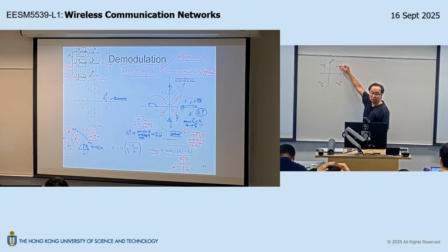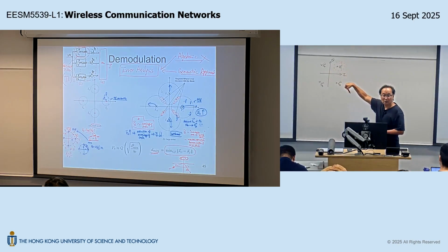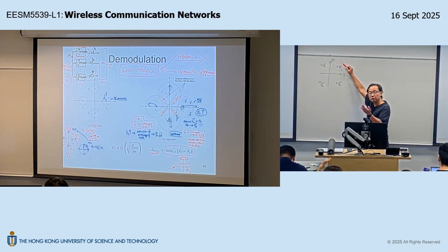S1, right? Because obviously, in this case, S1 will be the best explanation for the observation compared to S2, S3, S4, right? Since we assume you transmit S1, and your output is S1, you see that you don't make a mistake, right? Next time, if your observation is here, likewise, using minimum distance demodulation, your output will be S1.